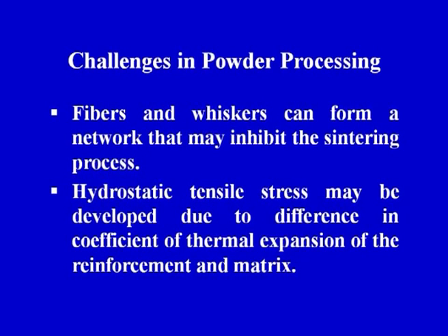The other challenge in powder processing is that fibers and whiskers can form a network that may inhibit the sintering process. We have already seen that agglomeration or fiber bundles may be formed during the process of mixing. That has to be avoided, and if these bundles or a network of fibers and whiskers are formed, the sintering process becomes difficult.